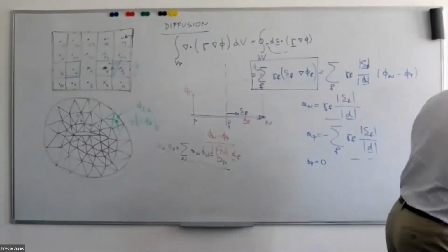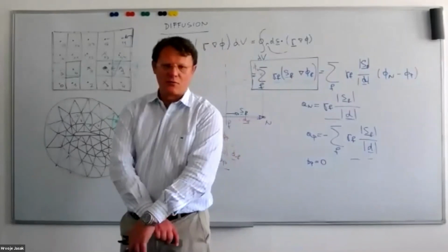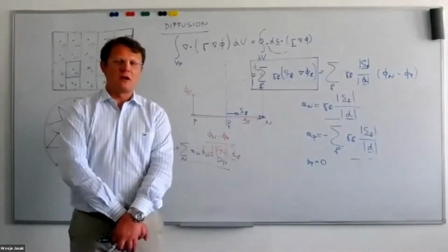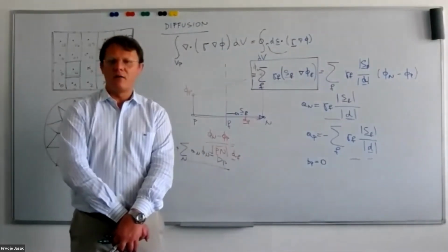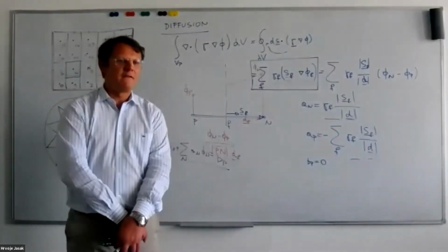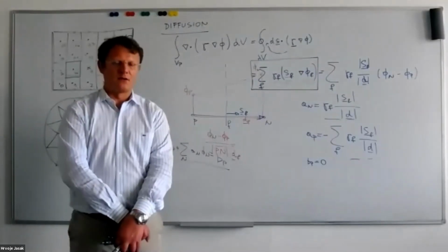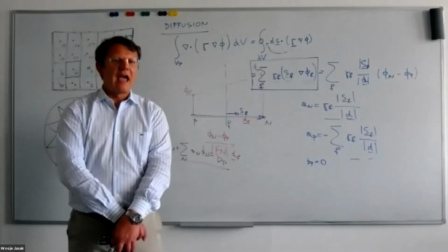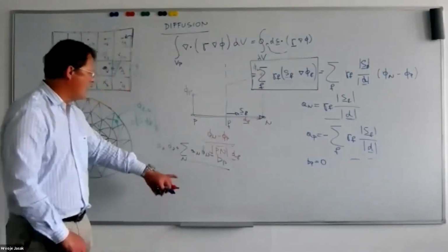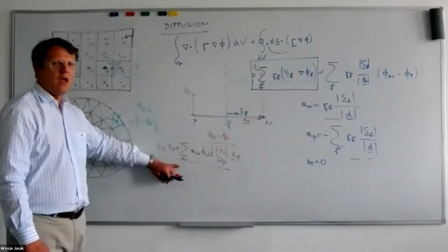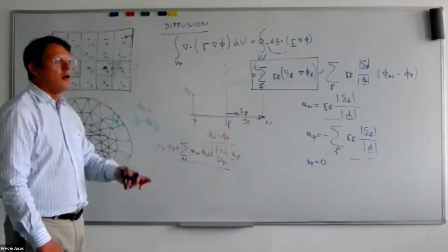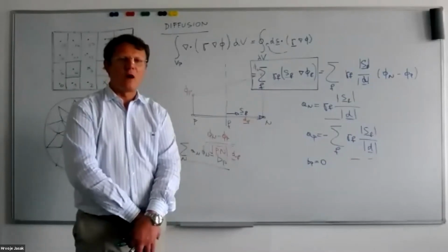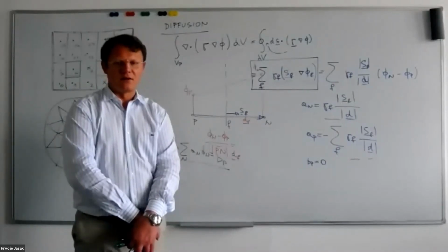That brings us to the end of the discretization procedure. And I hope I have shown you that there is no magic allowed. We have played very basic mathematics. We have gone through the volumetric and surface integrals. We have specified and integrated a shape function and created a system of linear algebraic equations which follow the behavior of my original partial differential equation. And quite frankly, this is where the fun starts.